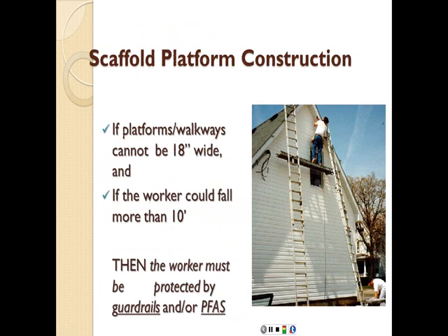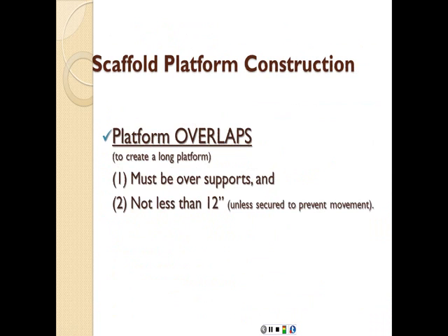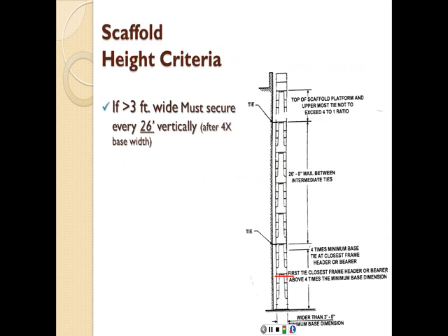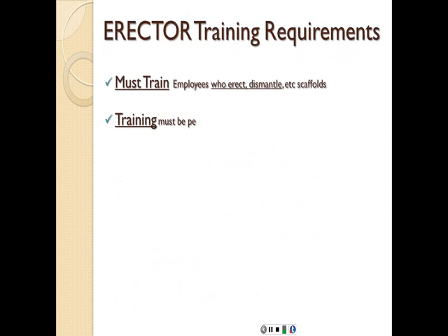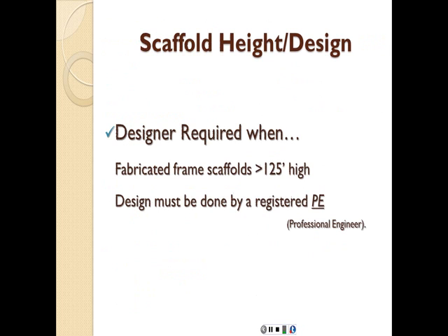And that also applies to things like in heavy construction. If you're going to have a bridge, for example, or something like that, then definitely that's going to be done by a designer. It's not going to be something for anyone to do. The design must be done by a registered professional engineer. If you remember, we have seen that when we were talking about excavation. If the excavation is going to exceed 20 feet, then the support is going to be designed by a professional engineer. Here's another area where a professional engineer is going to design some part of our work that we need to perform.